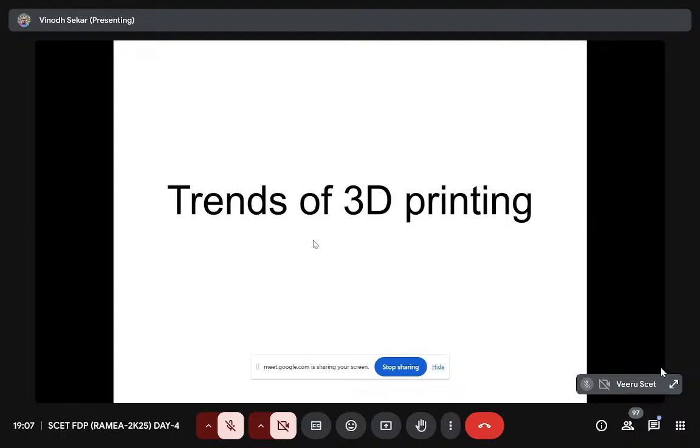Yes. Is there any FEA possible for 3D printing technology? Yeah, definitely. Because now, if you see, optimization is a very important aspect while designing for additive manufacturing. That's why we have brought a separate dimension. The separate domain is being brought under the design to facilitate additive manufacturing by the term DFAM. In DFAM, we do have different methods like topology optimization, generative design. These methods rely on finite element modeling based approaches, and they are advanced extensions of the finite element based modeling and analysis that helps us in designing and developing the products.